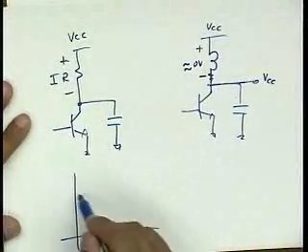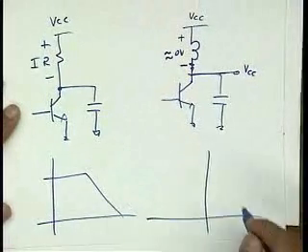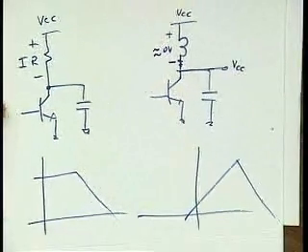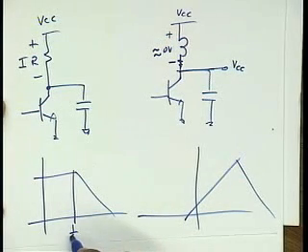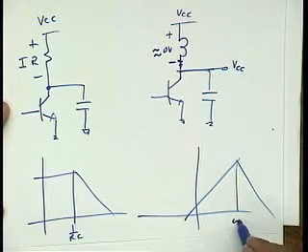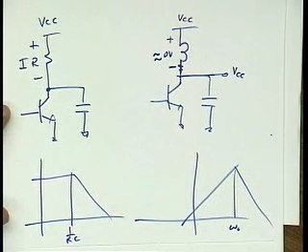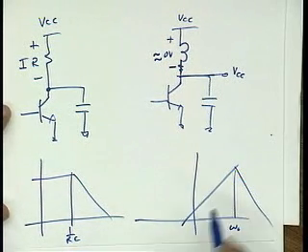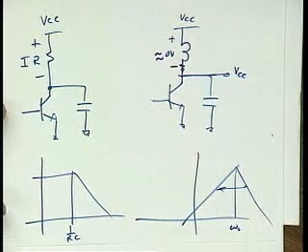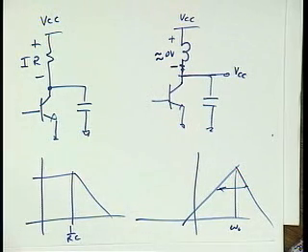So this method doesn't cancel a pole. No, what it does is it moves a pole, right? It's taking a low-pass pole and turning it into a band-pass pole. In other words, if I draw a picture here, the transfer function of this circuit looks like that. The transfer function of this circuit looks like this. So it's taking this RC pole and moving it to an arbitrary frequency, apparently arbitrary frequency, omega naught here. And what we'll find actually is the bandwidth of the circuit does not change. So we'll come back to that point.